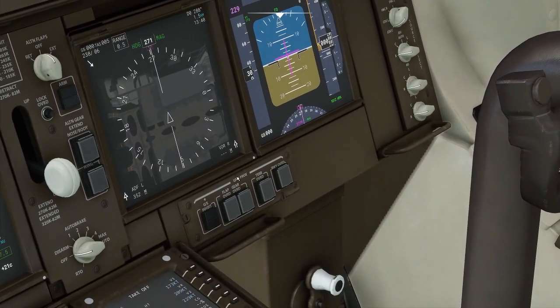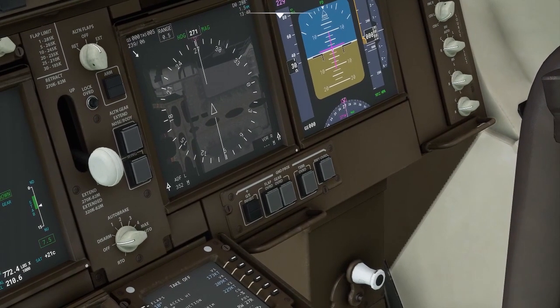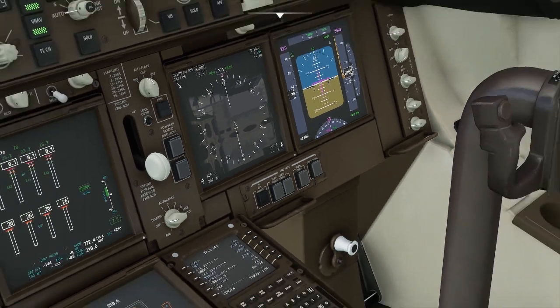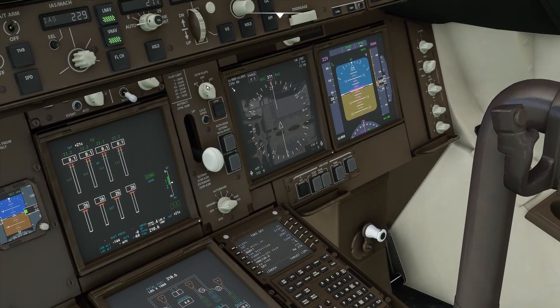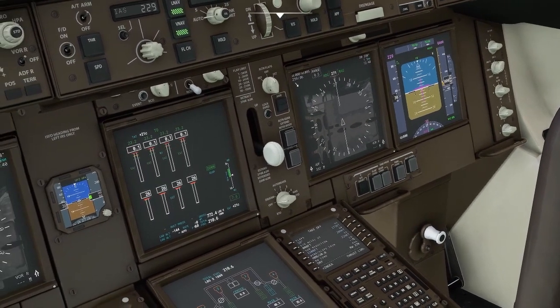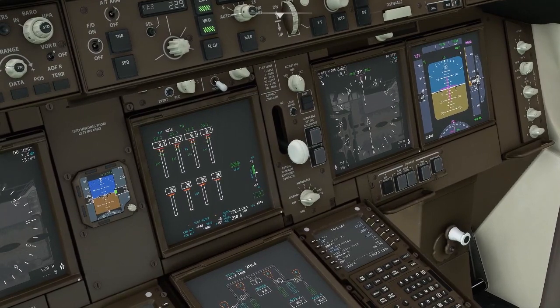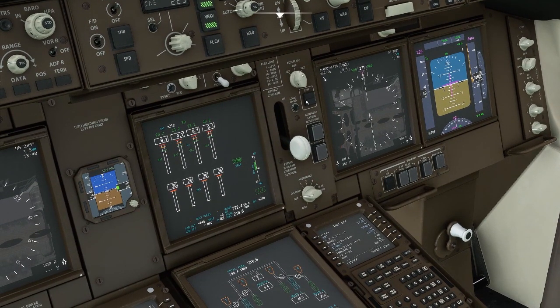Just you've got these ground prox override switches which would override warnings. So you press those for overriding certain things with checklists. If you weren't doing a full flap landing for some sort of problem you had, you might click flap override and stuff like that. These alternate flaps aren't working. You don't need to worry about them unless you've lost some form of hydraulic system which powers the flaps. And these are alternate gear extensions, which we also aren't going to worry about.